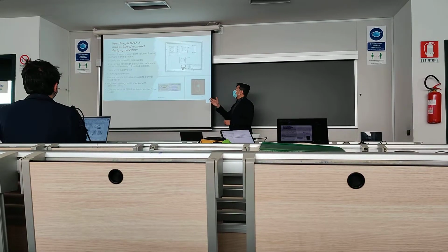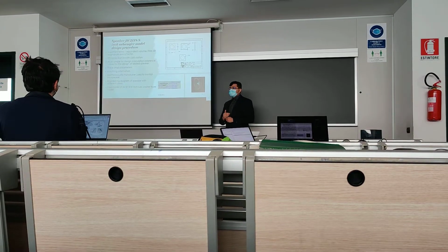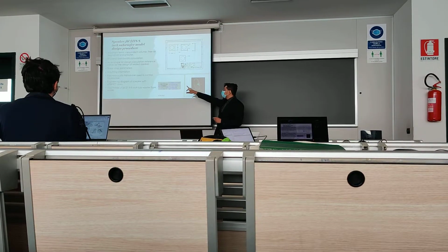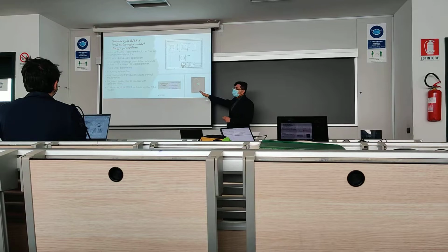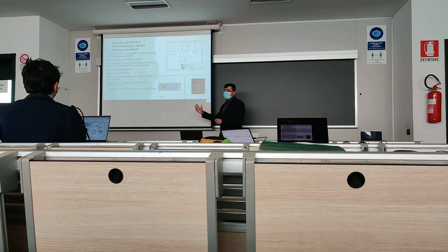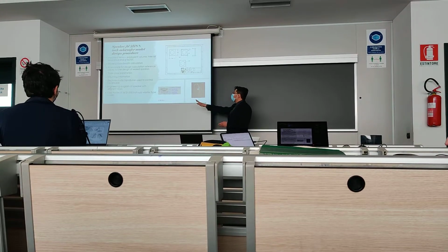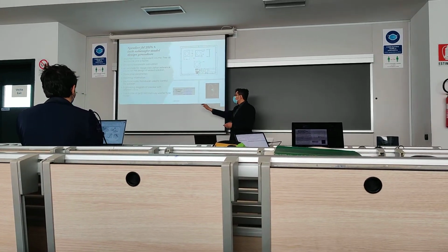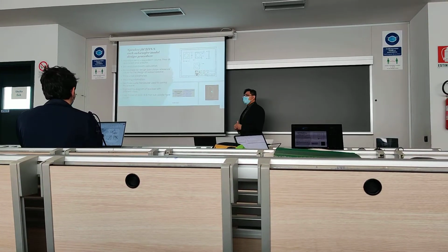Then we also have to study the Thiele-Small parameters. This is a sealed type of speaker, the best kind of speaker you can choose for this kind of direct exchange technique out of all other speakers. In this, you have to know the effective cone diameter, mounting depth, magnet diameter, magnet height, and linear excursion.